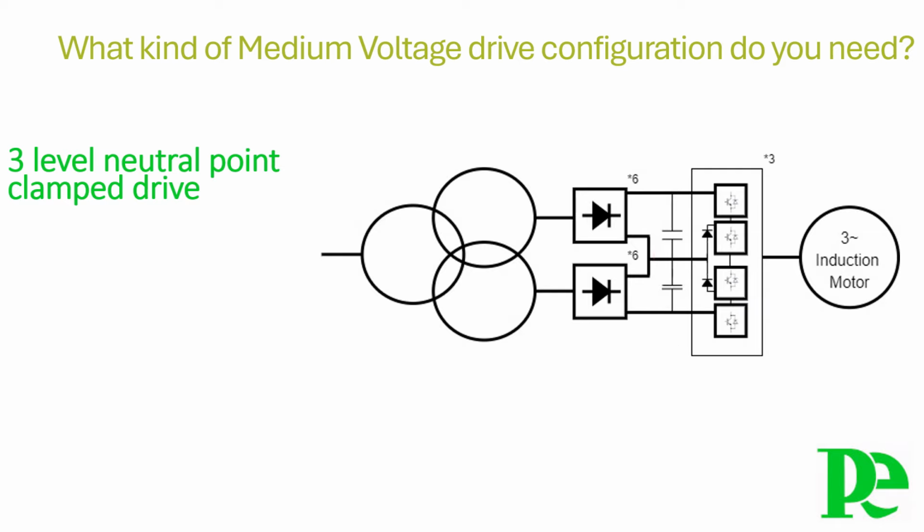Most of the time, this kind of drive is used in combination with a converter duty motor. The main reason for this is a rather high voltage rise in the output of these drives. In case of long motor cables, an output filter will be required to mitigate the risk of insulation breakdown caused by reflected wave voltage spikes. To reliably drive a standard direct online motor designed with standard insulation, the 3 and 5 level neutral point clamped drive will require a supplemental output filter.